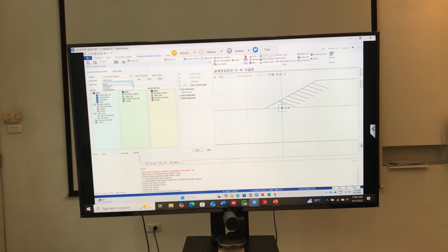So if it's initial stress, that means here you just activate stress. And what do you need to activate? You activate embankment, foundation, and you also activate ground boundary. Then now, I told you about self-weight. You can see here we have two self-weights. So you can choose any.